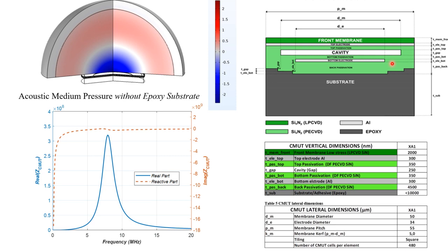So in response to the vibration, the counter vibrations are going to induce tensile stresses. Because of that, it might act as a bilateral CMUT. So the back passivation becomes a second ultrasound medium, just like you have at the front, that's the water. You might have the second ultrasound medium over here. That can be done in COMSOL if you include the damping losses in solid mechanics and select the PECVD, and you assume that the PECVD passivation is a homogeneous medium, and you can change the isotropic losses.